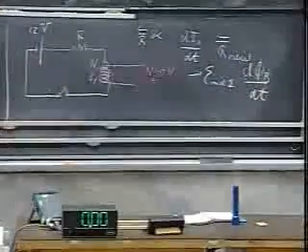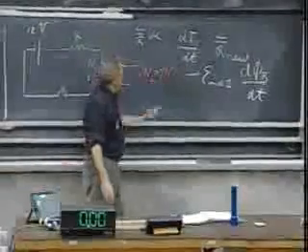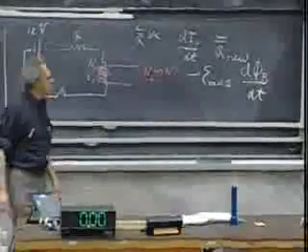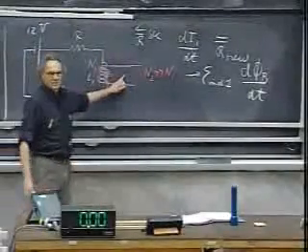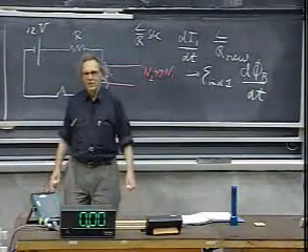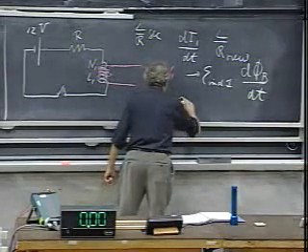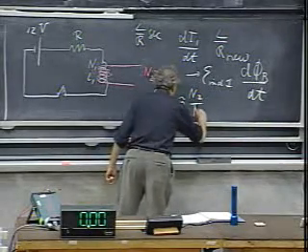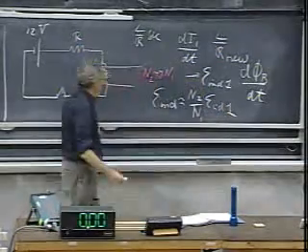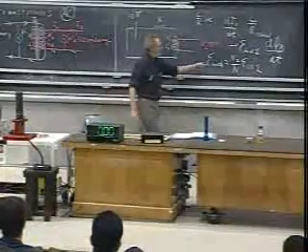You get an enormous change in the magnetic flux here, which is directly coupled to the current. And that induced EMF could be several hundred volts. But now look at the secondary. The secondary has an N2 which is way larger than N1. So the induced EMF in the secondary is very roughly N2 over N1 times the induced EMF in the primary. That was the ratio that we had earlier, the V2 over V1, remember, was N2 over N1.